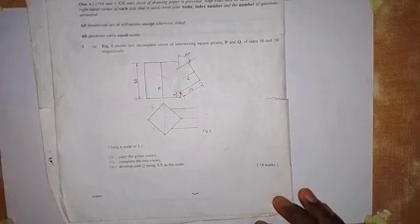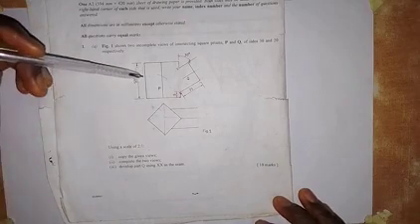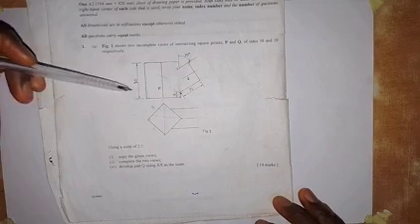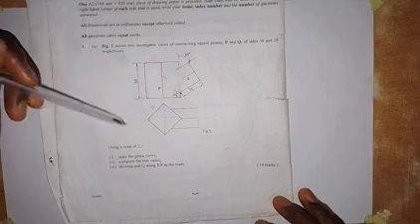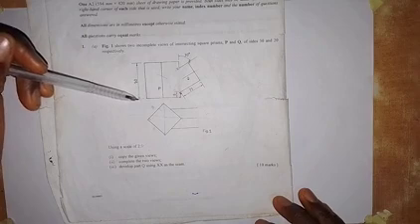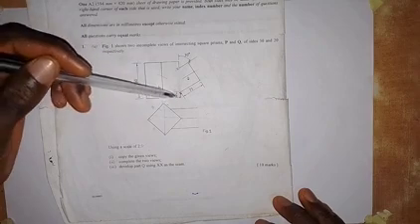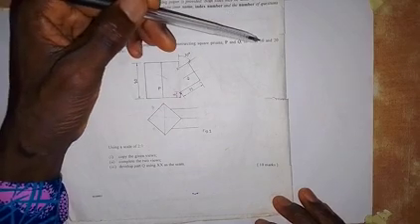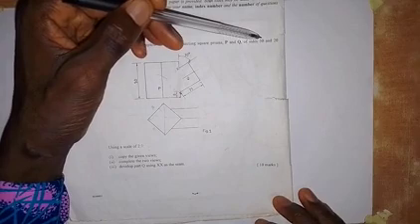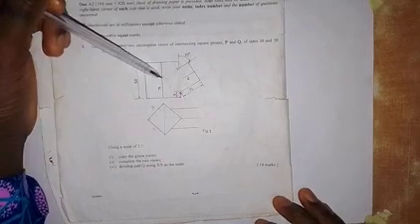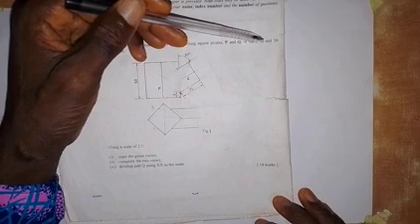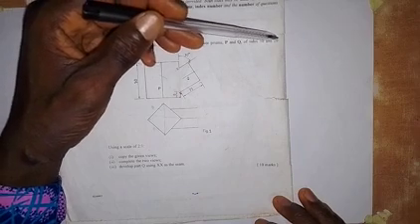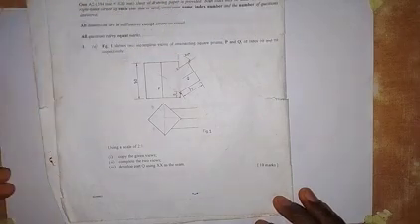As we are given the scale to use 2:1, what they expect us to do is to multiply each of these dimensions by 2. That means we have to multiply 50 by 2, 8 by 2, 35 by 2, and also the 30, the length of side of part P, by 2, and the length of side of part Q, which is 20, by 2.